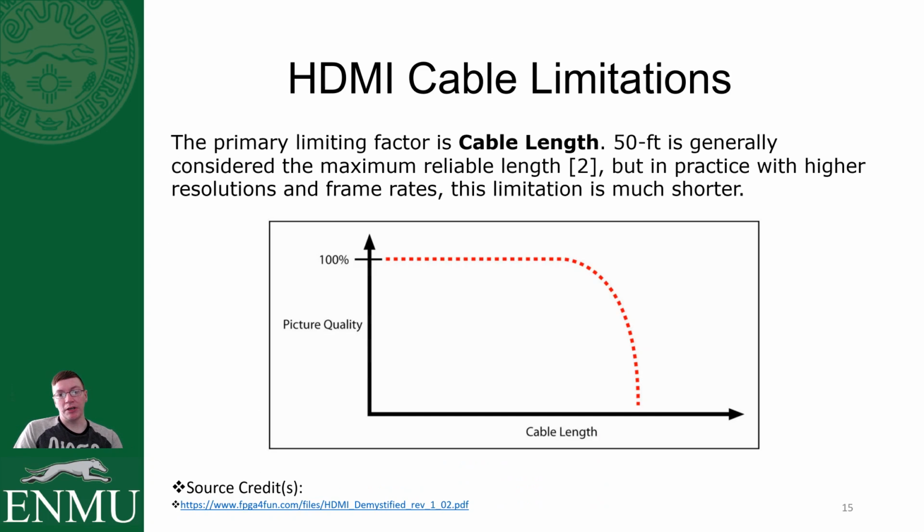Okay, so like I said, cable length is the primary limiting factor. There are no numbers on these charts because it varies greatly from one cable manufacturer to another. I could take two cables that are supposedly compliant with the same HDMI standard, and it is anyone's guess whether or not they're actually certified. There's a lot of people cheating out there, and they're using the HDMI logo even though they're not a certified HDMI adopter, and they have not sent out their hardware or their cables for compliance testing. So it's pretty difficult without some high-end test equipment and a lot of time to dump into it to find out if a cable really should have been certified or if it ever was certified in the first place.